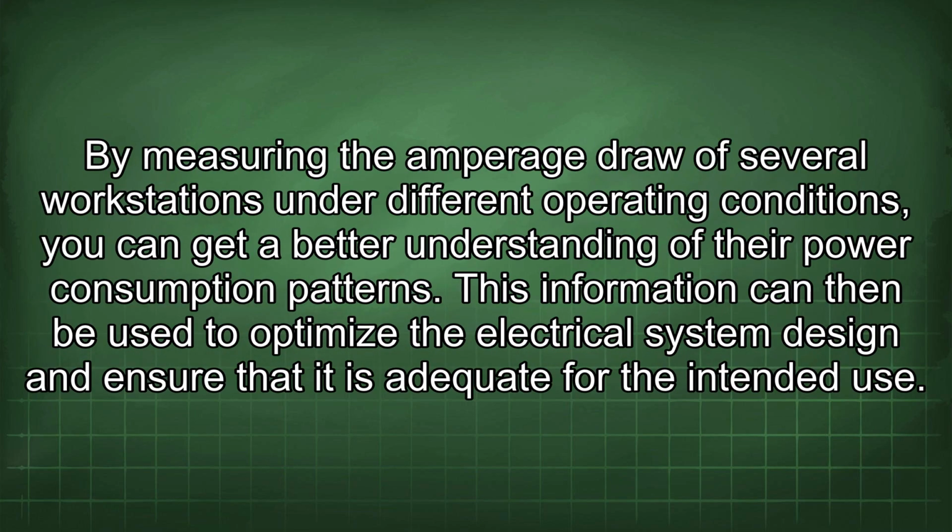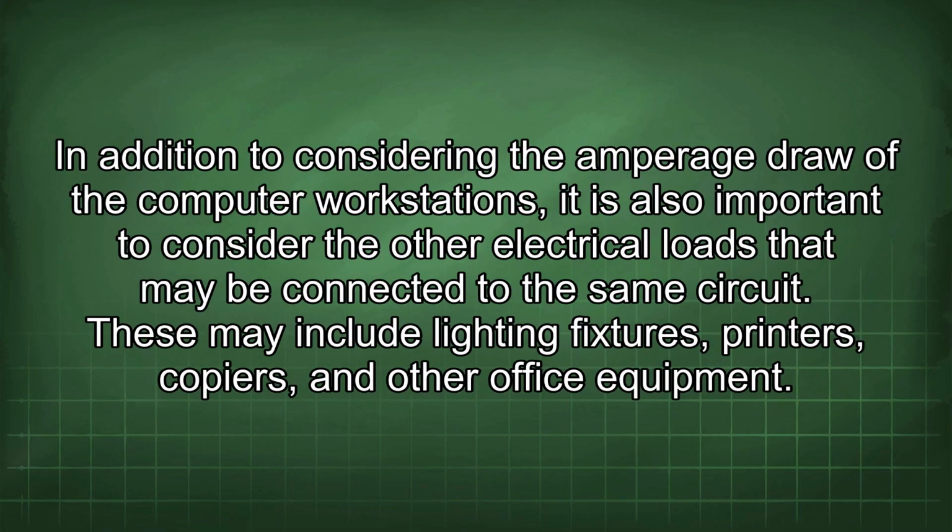By measuring the amperage draw of several workstations under different operating conditions, you can get a better understanding of their power consumption patterns. This information can then be used to optimize the electrical system design and ensure that it is adequate for the intended use. In addition to considering the amperage draw of the computer workstations, it is also important to consider the other electrical loads that may be connected to the same circuit.